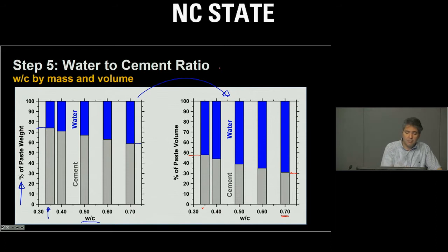This is how we make concrete. This is where engineering properties are. This volume ratio is really governing the engineering properties. And you can see that as the water cement ratio increases, an enormous volume fraction of the system is made of water. And therefore, the mechanical properties and durability of the system degrade very rapidly with increasing water to cement ratio.